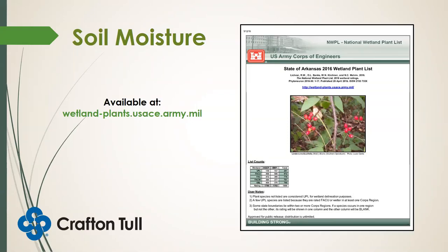Hey, Eric, I can speak to that. And yes, it is very effective. One thing that we do is we work with a really cool vendor called Profile. So what we'll do is we'll take a sample of the soil before we hydroseed it, and they'll test it for us. They'll let us know if we need to add any additional nutrients like nitrogen and phosphorus to the hydroseed mix.